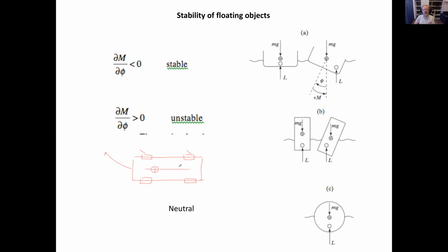If the CG would be in the back, like in some of the cars, then it actually will try to turn more, to lose the back. This is called oversteer. So this is oversteer, this is understeer, and it depends on the CG. Now there are lots of Porsche fans over there. What the Porsche guys do is put a bigger wheel here, to compensate for the shorter moment arm.